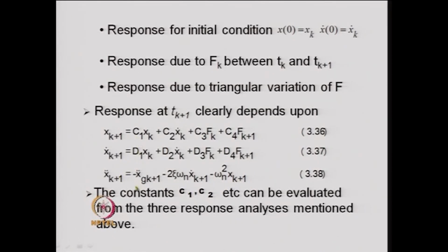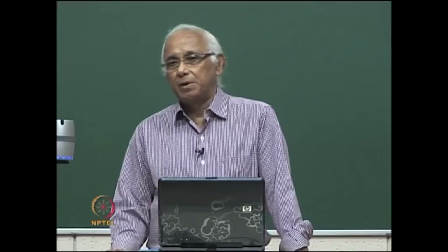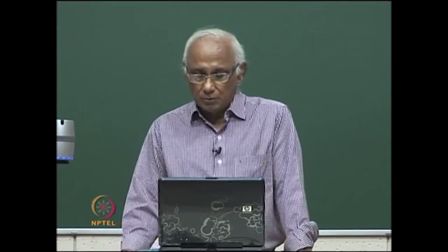So, using these 3 equations, one can get at any time step k plus 1 all the 3 quantities, that is, the displacement, velocity and acceleration, in terms of the displacement and velocity at the previous time step k, and the forces acting at k and k plus 1, which are eventually known.